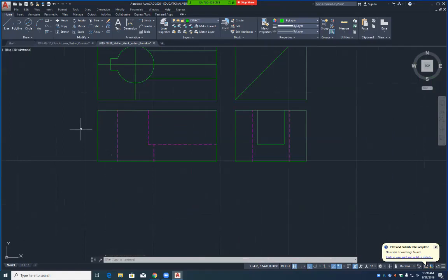Okay. Now to finish drawing this, I need to draw a line from here down to here, right? Now, would I go ahead and go through all the problems of extending it, trimming it, and changing it? Or is there a way of maybe making it in half the steps? You can offset. But do I know that exact distance? No, but you can snap from one point to another point. But I can copy from here to here, can I? Right. You bet. So copy here from that point over to that point right there.